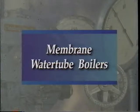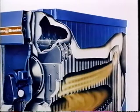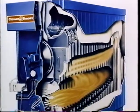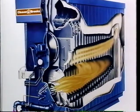Membrane water tube boilers. Membrane water tube boilers are compact boilers used where space is limited. The vessel of membrane water tube boilers consists of formed membrane tubes and downcomers connected to upper and lower drums. The boiler vessel is gas-tight, insulated on the outside, and covered by casing constructed of removable formed steel.